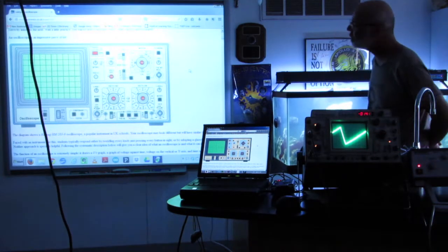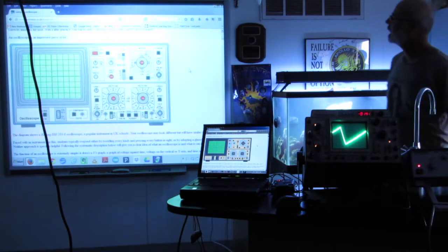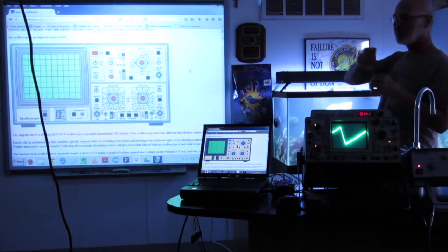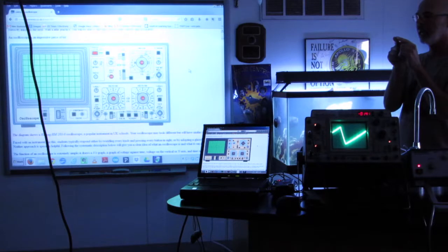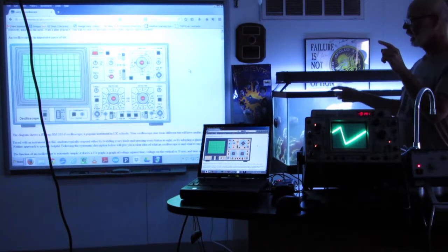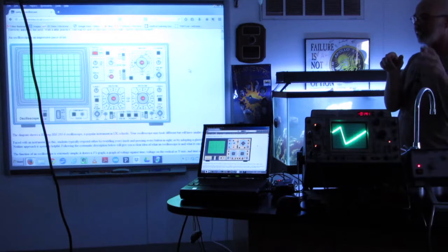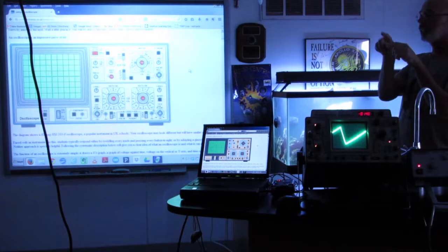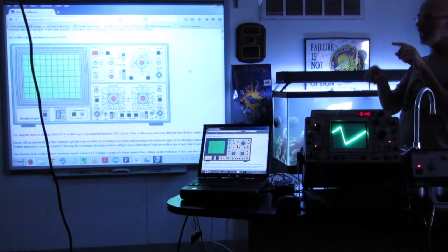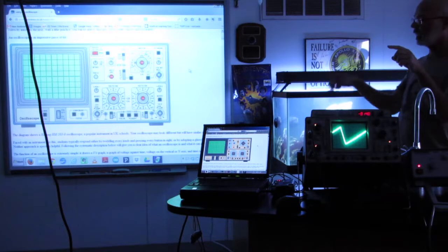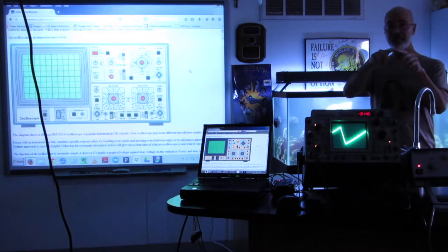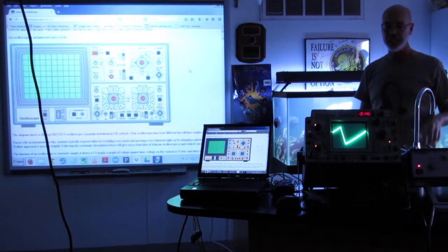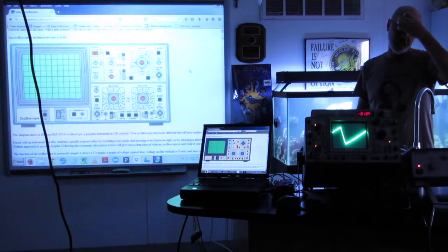So the reason you're getting a stable display is because, if it's set at 1 volt, the scope is waiting until the voltage of that sine wave hits 1 volt, and then it starts its sweep. And then it resets, and then it waits again, and some arbitrary voltage will come along. As soon as the sine wave hits 1 volt again, it triggers again, and lo and behold, it's exactly following the same path every single time, because it's always starting at the same place, the same phase, so to speak, 20 or 30 degrees into the sine wave. So it always triggers at the same point.